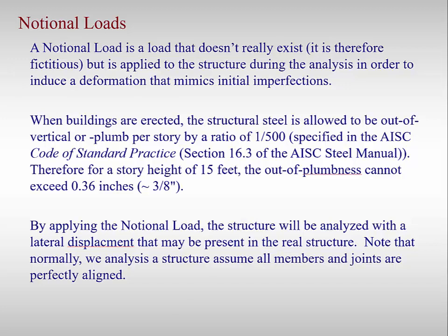And when buildings are erected, the structural steel is actually allowed to be out of vertical, out of plumb per story by a ratio of 1/500. This is specified in the AISC steel manual, but it's in the Code of Standard Practice, which is section 16.3, instead of 16.1, which is the specifications.